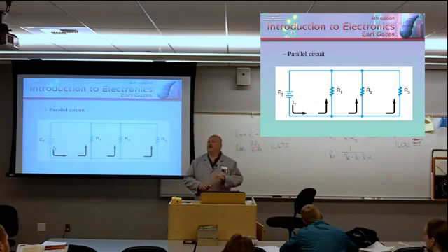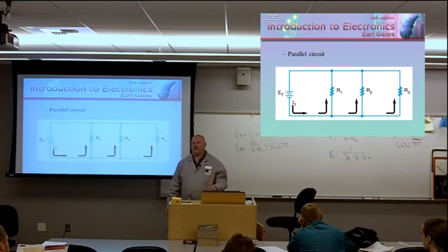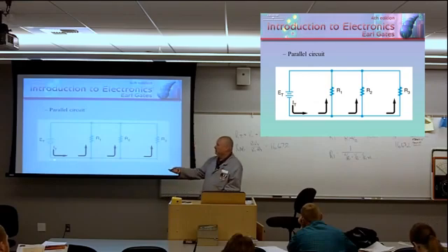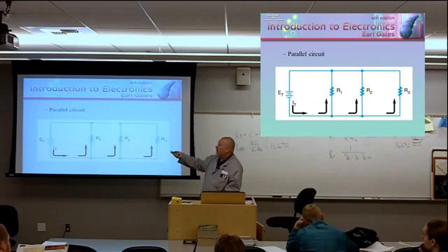A series circuit was also known as a voltage divider. A parallel circuit is going to be known as a current divider. Because what happens to current in the circuit? This total current here gets divided here, at this node, and here. Then current gets divided here and here. The current flowing through R3 and the current flowing through R2 join up at this node and flow on to this node. This current plus this current equals total current.